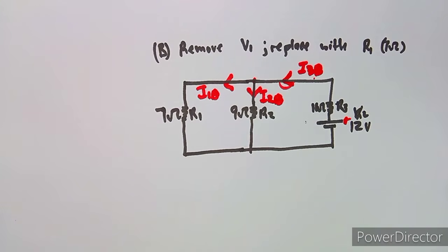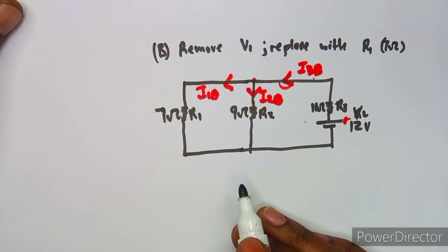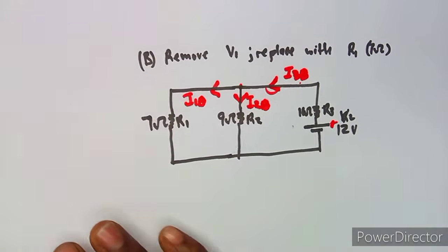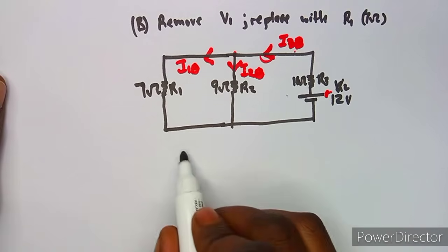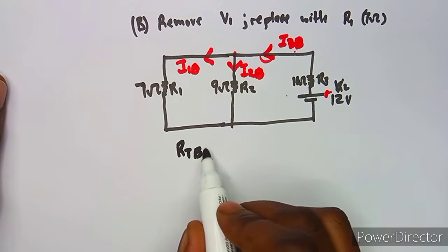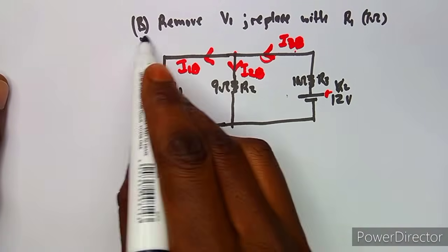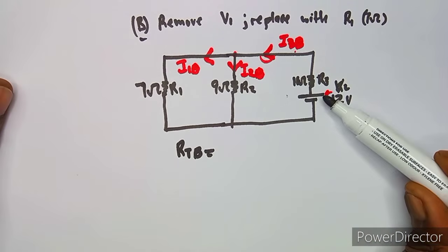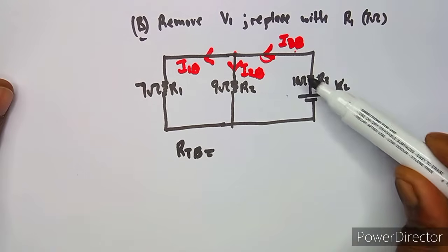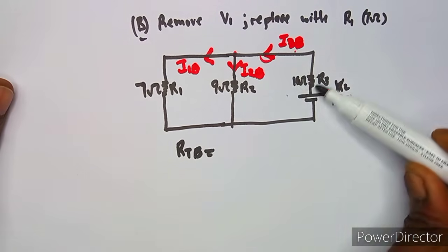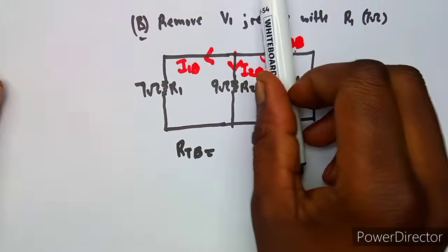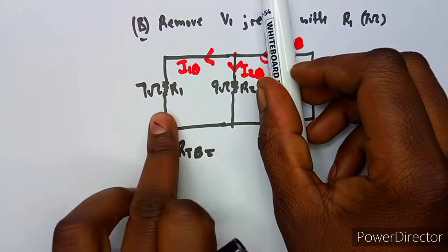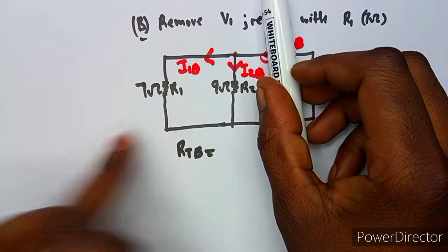Still following the last stages that we had, we have to calculate the total resistance of the circuit so that we can calculate this current. So what will be the total resistance of the circuit this time due to condition B? Because you have got a voltage source, this is going to be in series with these two, which are in parallel, so we use product over sum.